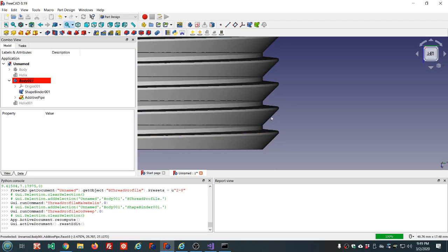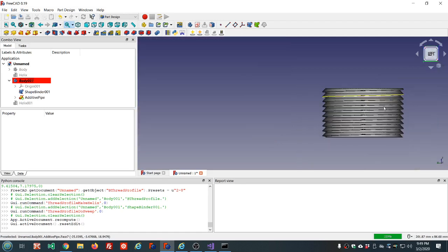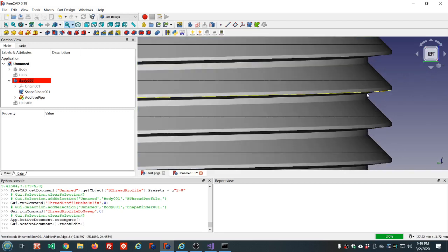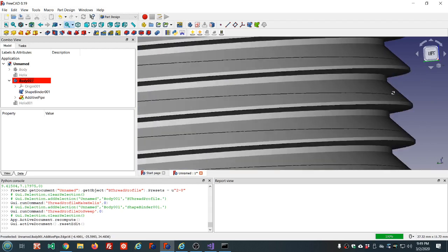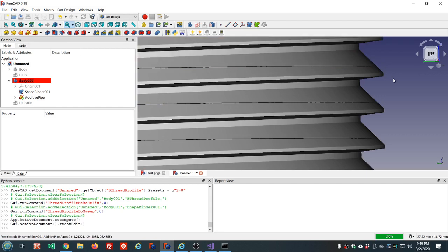So with this 45-degree angle, you'll have a better chance of printing this without support and not having problems, because as your layers move up, it's not too steep of an incline. But if you print it in the other direction, then you would have the opposite situation. You have a lot of overhang here. I think it's a 7 degree by 45 degree is what this profile is.